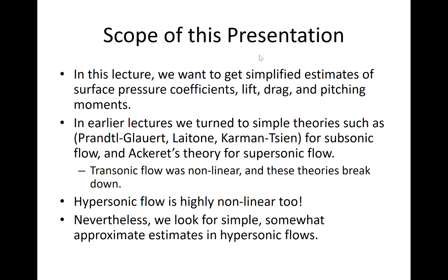So in this lecture, we are going to get some simplified estimates of lift, drag, and pitching moments. In earlier lectures, for subsonic flow, we used Prandtl-Glauert, Karman-Tsien, and Laitone. For supersonic flow, we used Ackeret's theory. We said that transonic flow is nonlinear, so these theories break down. In hypersonic flow, these theories also break down. So we don't have these simple theories that we can apply in hypersonic flow. Fortunately, there are some approximate estimates in hypersonic flow that we could do. So we are going to cover those in the rest of this presentation.